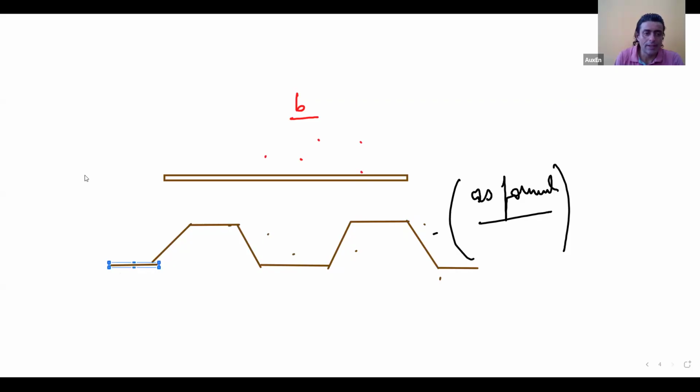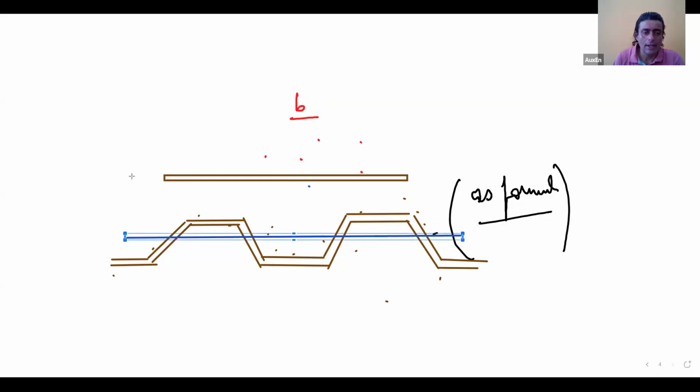So this is the same thickness, but what I did is, is the concept understood by everyone? This is very important to understand. See, the concept is very simple. In my normal construction, I'm using an RCC, I'm using a formwork, then I'm putting reinforcement, then I have to remove the form. Sometimes to support the formwork, I have to put so much scaffolding. It's all very time consuming. So I thought, why not use the formwork and then use it as reinforcement also.